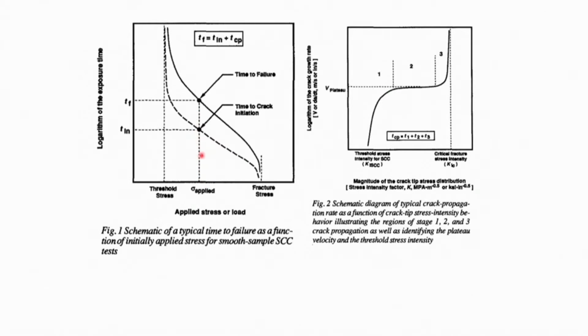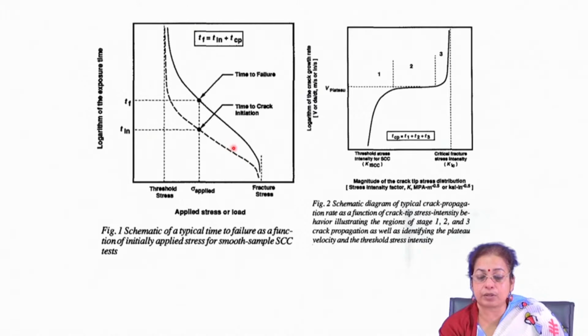So, this is very important. When the stress is quite low, the time required for initiation and the time required for failure are quite high. As you go on increasing the stress, the time gap between crack initiation and crack propagation decreases. And as you increase the stress further, it again decreases to a large extent and finally it fails.